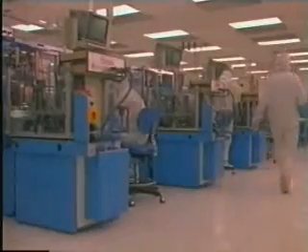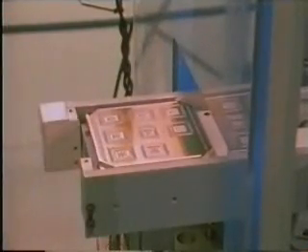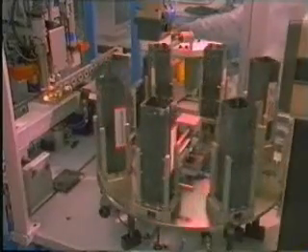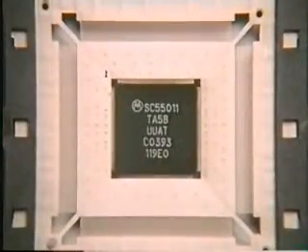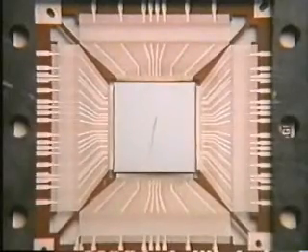In die bonding, this manufacturing facility uses 3 separate machines to accommodate the 3 sizes of fast chips used in the multi-chip units. The die are bonded to the high-density signal carriers using a chip-to-substrate interconnect called Tape Automated Bonding, or TAB. This TAB chip is densely packed with leads on all 4 of its sides. From the back, we see the inner leads fan out to the outer leads where the bonding will occur.